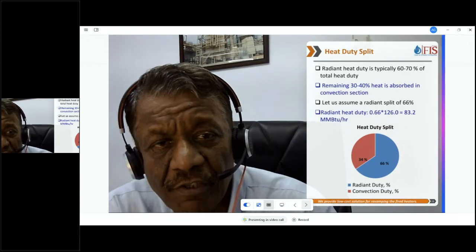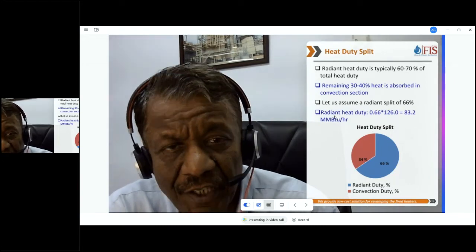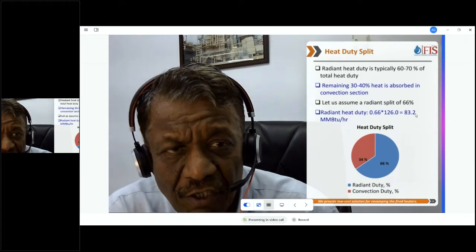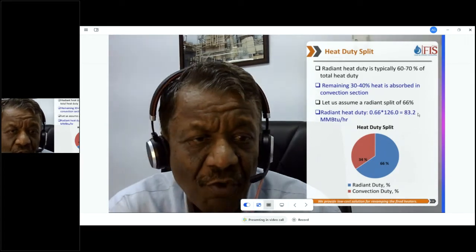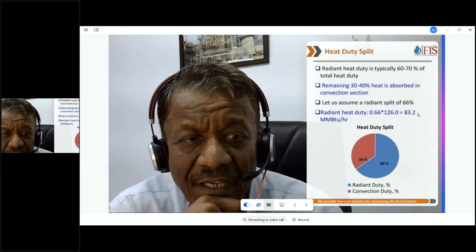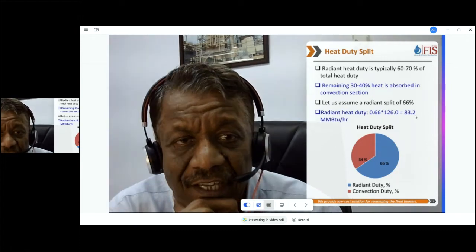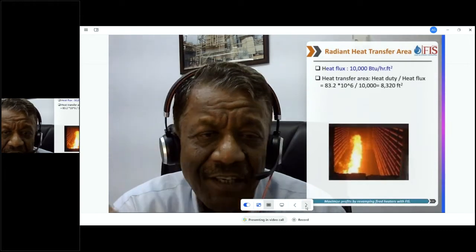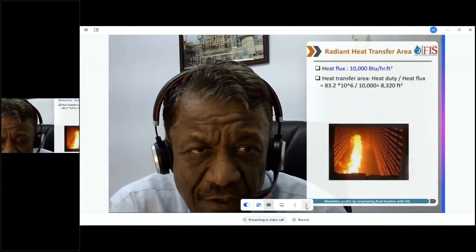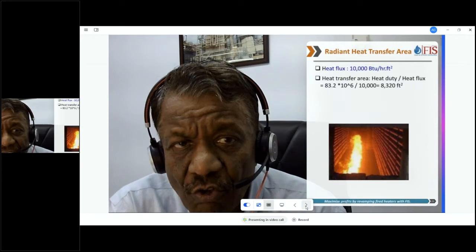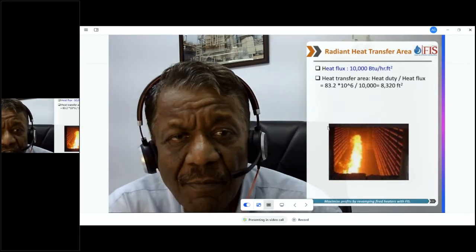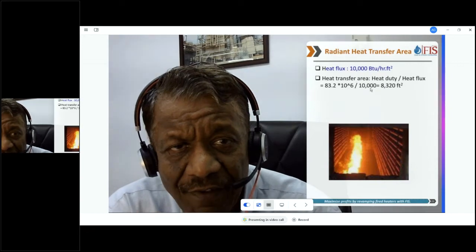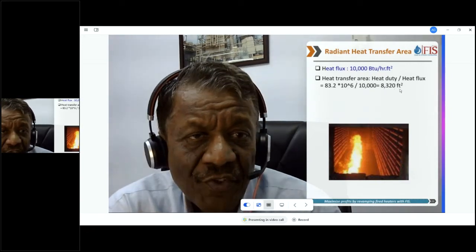So it shows you 66% heat duty. The radiant heat duty is 0.66 times 126, which is about 83.2 million BTU per hour. That's our radiant heat duty. Then we selected a heat flux of 10,000. Once we select a heat flux, we know how much surface we have to provide. Radiant heat duty divided by 10,000 gives 8,320 square feet.